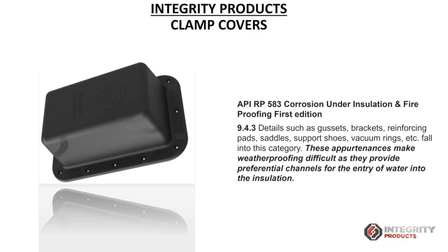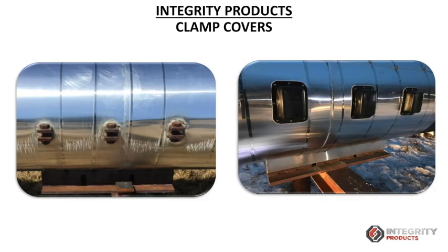In this figure on the left side, we can see some clamps projecting out of the insulation, and also certain gaps in the cladding, the jacketing. Those gaps could be areas where moisture can intrude, and these clamps could be locations where weathering is impacting and deteriorating them. Also, the temperature of these clamps is high compared to the ambient conditions, so it would be a location of heat loss from the piping system to the atmosphere.